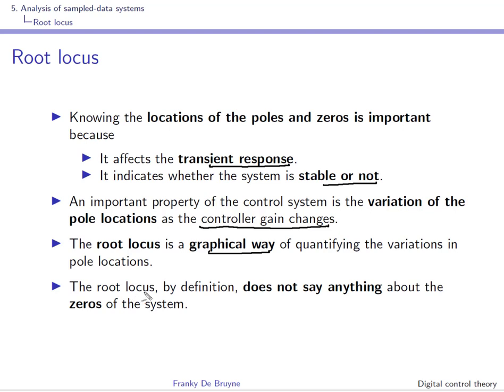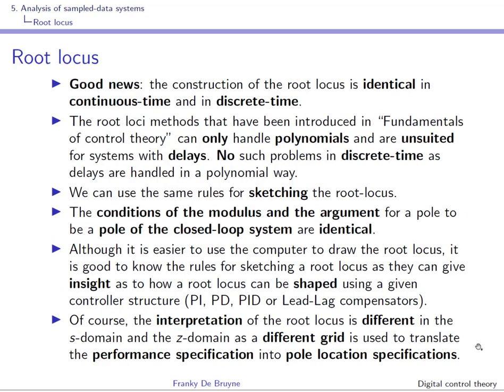The root locus, by definition, is the roots of the denominator. The root locus does not say anything about the zeros of the system. The good news is that the construction of the root locus is identical in continuous time and discrete time.